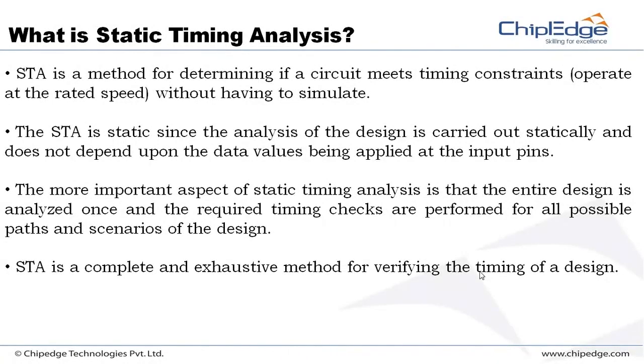The greatest advantage of this is it will check all the paths that are there. For example, if you consider your regular test bench writing the test vectors, right, some paths might have been missed, so the data might not have even entered into that path and you might have missed checking that path. But STA is not so. It is very exhaustive, complete. It will check all the paths in the design.